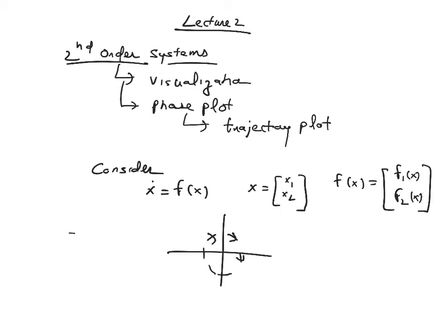I'm just giving an example. For example, an inverted pendulum without friction will have trajectories like this. You can see, it makes sense. It doesn't matter wherever you start, you will just keep oscillating. I'll connect all the dots later on, but if this is x1 and x2, which is the inverted pendulum with theta and theta dot, two states, right? Whatever initial condition you choose, let's say I start here, you will keep rotating on that, without friction. So these will be the trajectories of an inverted pendulum, not on a cart, just a simple inverted pendulum.